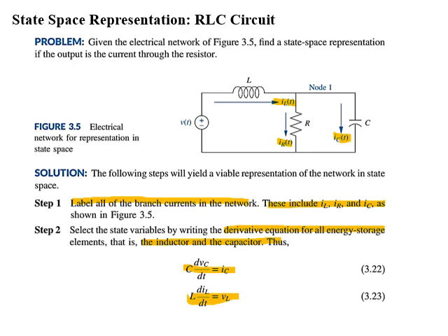Now both these equations represent first order derivative of our state variables, but in state equations, first order derivative of state variable is equal to linear combination of states and input. Now to complete this state model, we will use Kirchhoff voltage law and Kirchhoff current law.